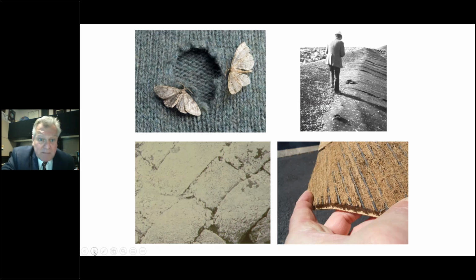As far as biologic is concerned, we're very concerned twofold, one from animals, but the second from microbes. So you'll see both of these in the biologic section of the guide. So you'll need to know what the extreme cases are. Moss will eat the natural materials. We had birds inside the polypropylene. You have fungi and algae. Very few things eat the polymeric materials as far as microbes, but we do have a lot of vegetation growing into the annulus. We like that with some geosynthetics, we don't with others.